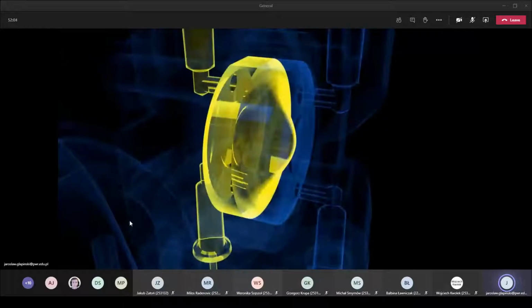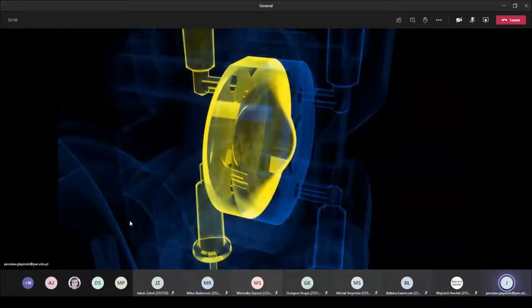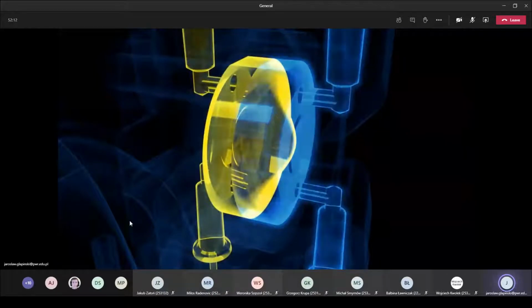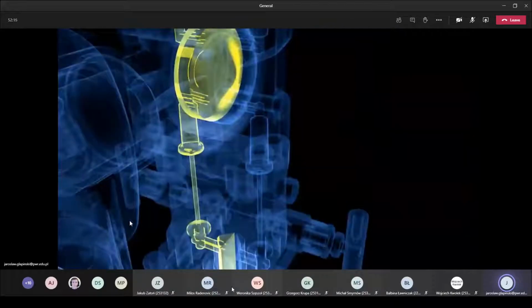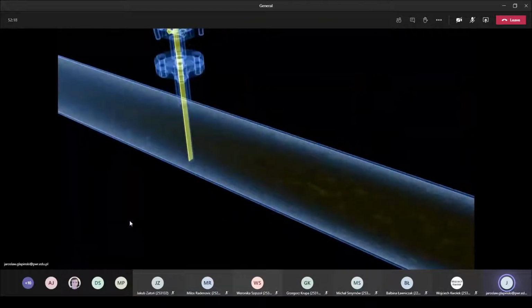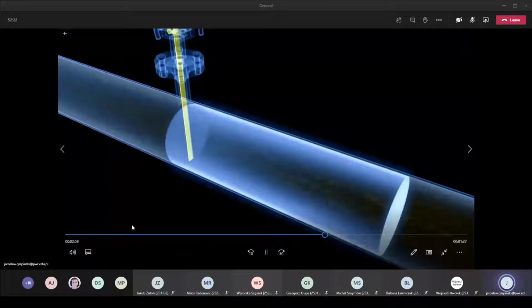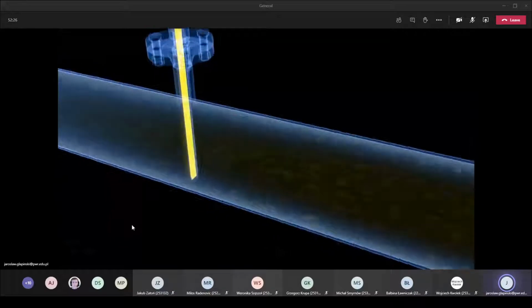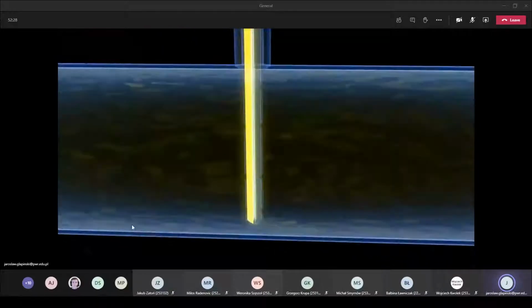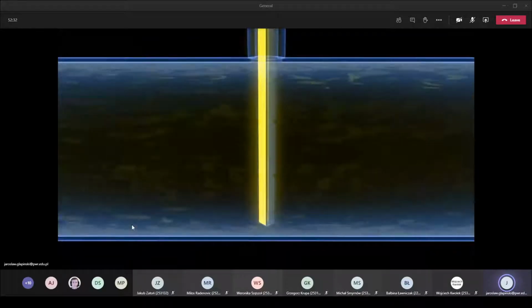As a result, different values are detected in the pressure chambers of the sensor. Higher pressure against the flow and constant pressure on the rear of the pitot tube. This pressure difference is a direct measure for the flow velocity and thus the mass and volume flow in the pipe. The higher the flow velocity and therefore the dynamic pressure, the greater the differential pressure measured.